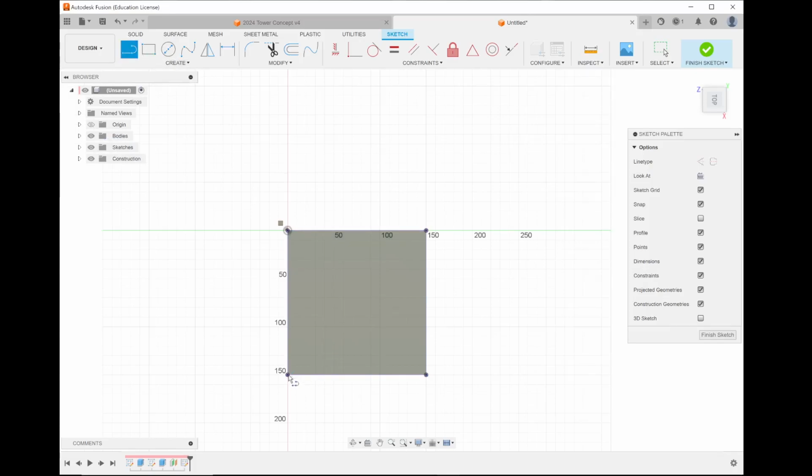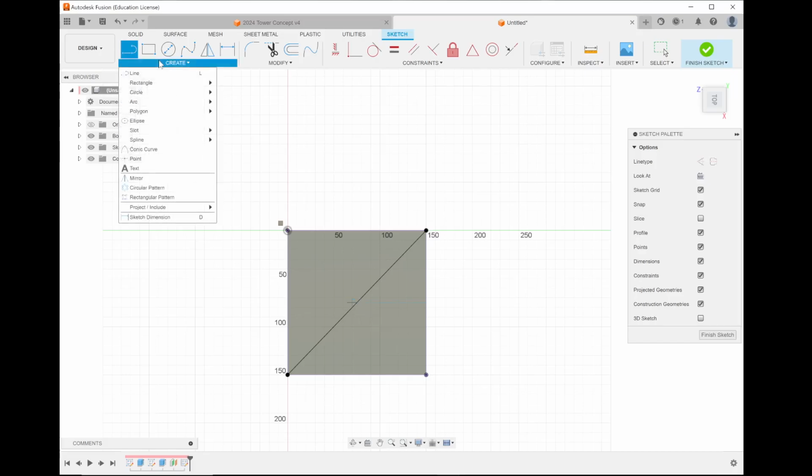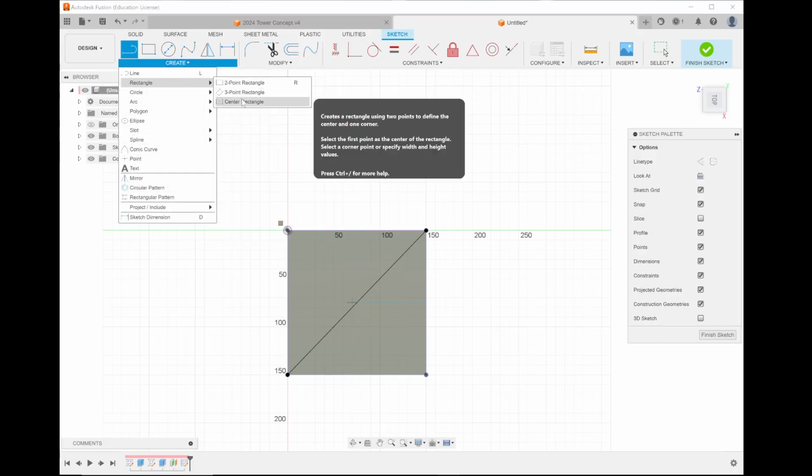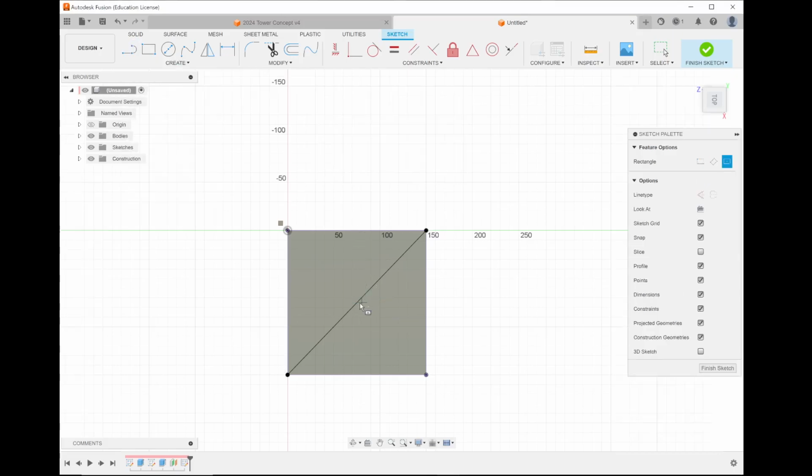Then we can do a line. And if we do this, now we should have, that should be the middle point of where our tower is. So we can go rectangle, rectangle center. If we hover the line over here with that blue triangle, we can now make a rectangle. And the shape of this rectangle, the cap is 75, 75 by 85. So 75, 75. So you have to be at least that much.